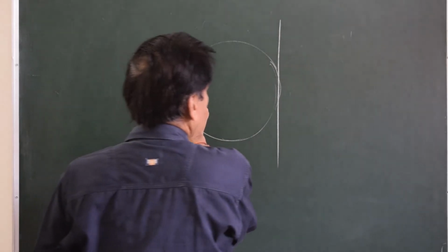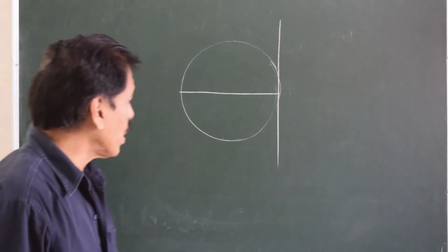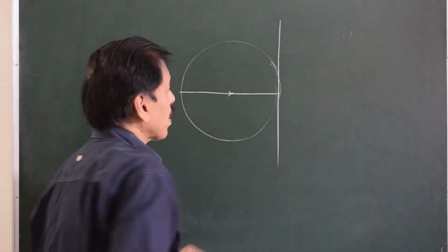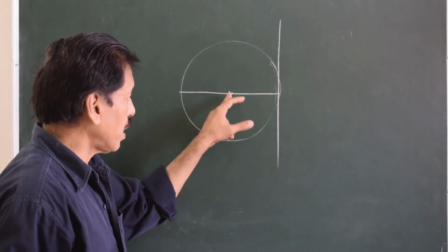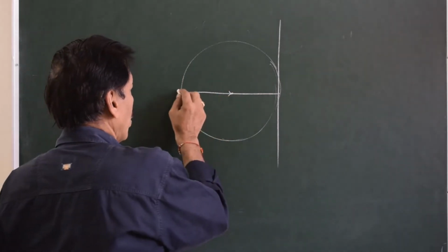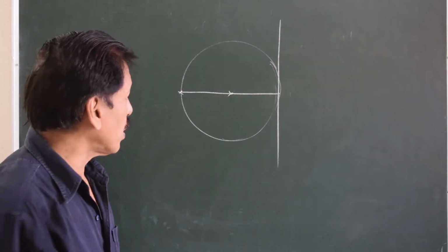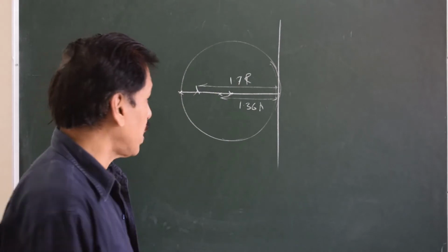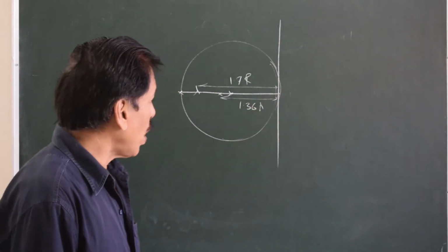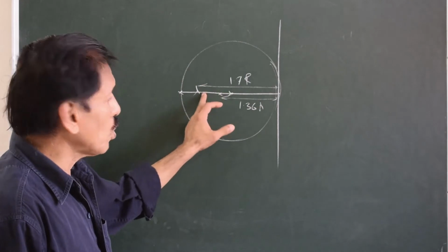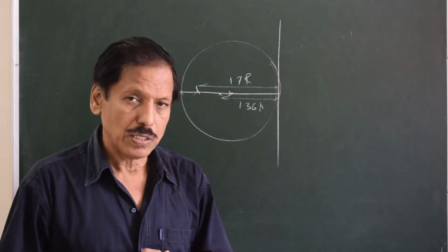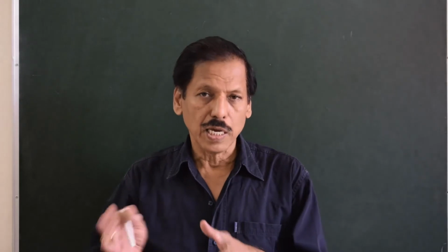It looks like a gnomonic or a stereographic projection with a difference: instead of the source of light being at the center or at a point diametrically opposite, the projection point is 1.36 times the radius to 1.7 times the radius from the tangent point. The projection point is chosen in such a way that the area of interest is projected with maximum accuracy.